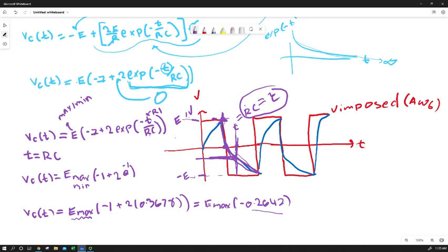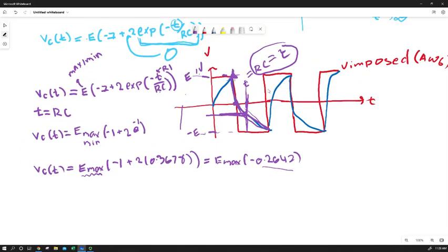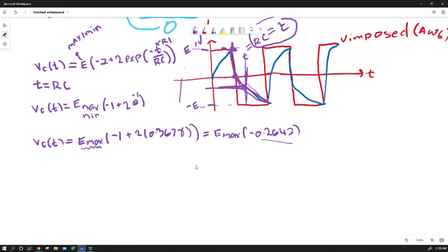So depending on the value you choose for R or C, your measured tau will be closer or further away than your calculated value. So you can actually decide. Theoretically, you could use different values of R and C to get the same tau: high resistor, low capacitor, or vice versa.